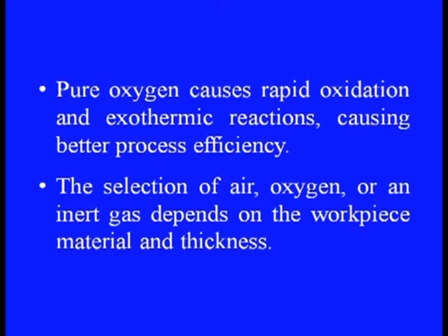Pure oxygen causes rapid oxidation and exothermic reactions, causing better process efficiency. The selection of air, oxygen or an inert gas depends on the workpiece material and thickness. Now, let us come to the material properties and environment. This includes surface characteristics such as reflectivity and absorption coefficient of the bulk material. Additionally, thermal conductivity and diffusivity, density, specific heat and latent heat are also considered.